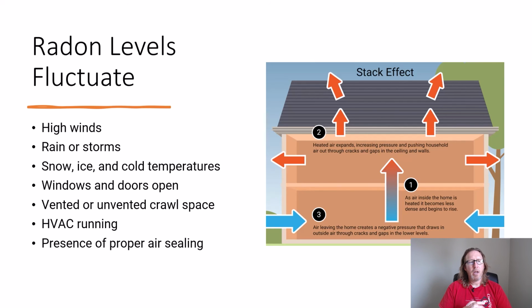Make sure that your HVAC is not running in most cases for the test, but that's kind of a hard thing to do, especially if these tests require 24 hours, but that can also throw off the test. Improper air sealing can also throw off the test. If you're running your bathroom fans, for example, it's going to mess up the test.